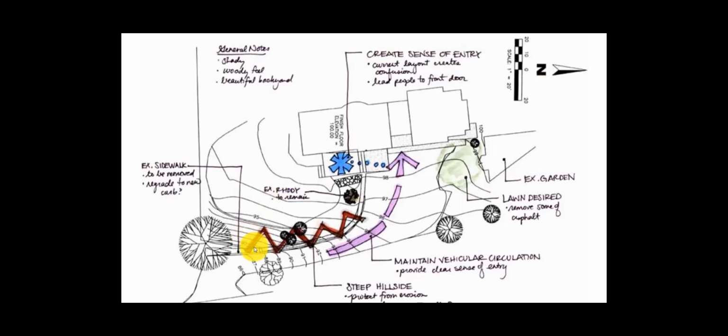These lines down here we're going to be talking about a little bit later, but you can see these kind of curved lines that have numbers on them. That's the elevation of the ground. So you can tell here that the ground is sloping up towards the building, or sloping down, because 98 is the high point here at the building, and then it's sloping down towards an elevation of 87. Each one of these lines, these contour lines, represents a different level of ground.